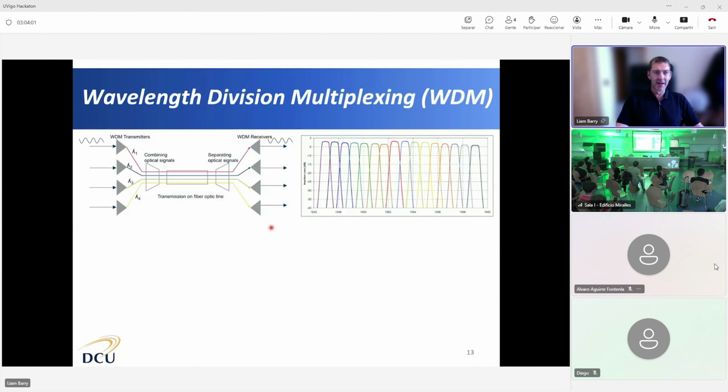If we think about how very high capacity optical signals are sent, it's a very simple technique known as wavelength division multiplexing. Its analogy in RF is where you may be sending multiple information signals on different RF carriers, and that's called frequency division multiplexing. In the optical domain, we talk about wavelength division multiplexing. Essentially, each wavelength can carry an information rate of 25, 50, 100, 200 gigabits per second, and then you can stack up many, many wavelengths and send them all on a single fiber.